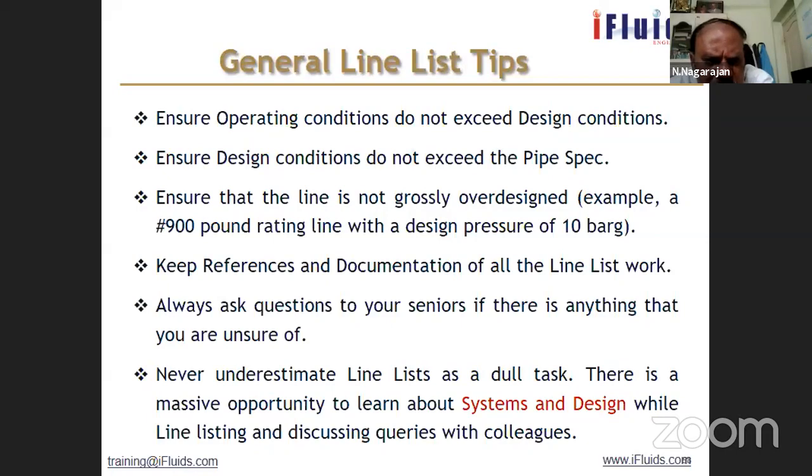Okay. Keep the reference documents for all the line list work, your hydraulic calculations and various heat and material balance. All those documents are the reference documents for line list. You keep them all in separate folders, and you should have access to these anytime.